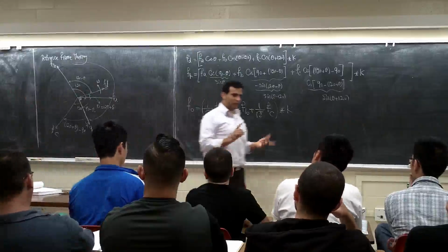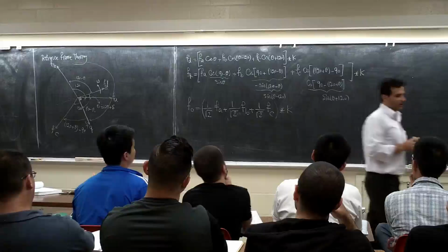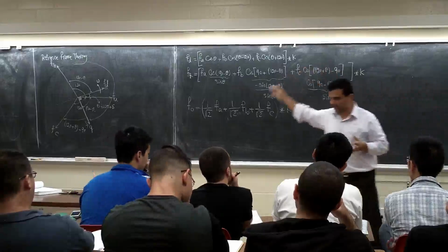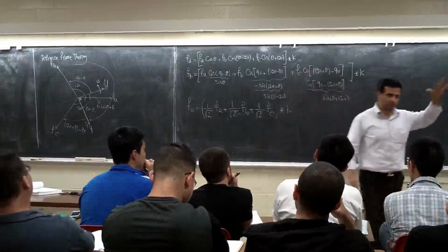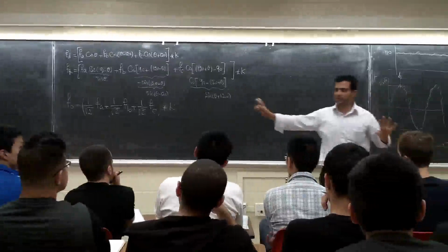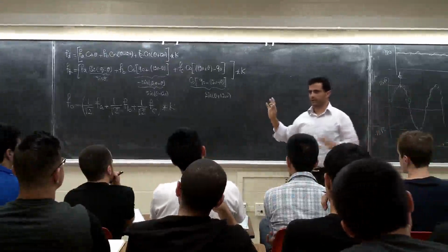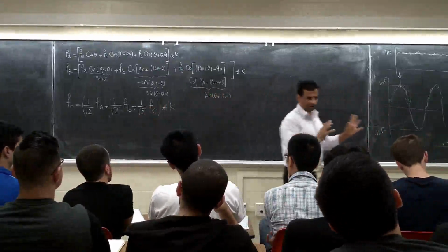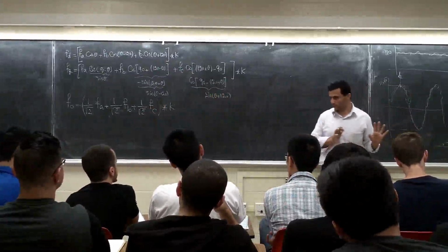You look at different books, you see different K values, because some people go with this concept. They say, I have this ABC system here and I'm coming to this DQ system. I want to keep my power constant. If I had 1 kilowatt here, I want to have 1 kilowatt here in this system. That's one way to go.